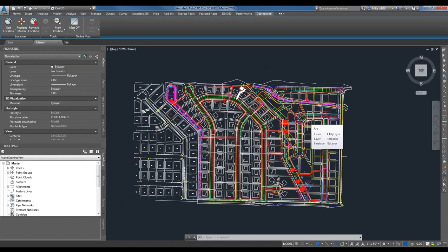However, in Civil 3D, we use COGO points, short for coordinate geometry points. They're a little bit different from those normal AutoCAD points. You could have plenty of properties associated with them. So you could have point numbers, point names, descriptions. So if you are surveying out in the field, you can bring in points with descriptions. You can tell them apart. So you can do top of curb, bottom curb, center line of the road, etc. So COGO points do allow you to have a little bit more customization.